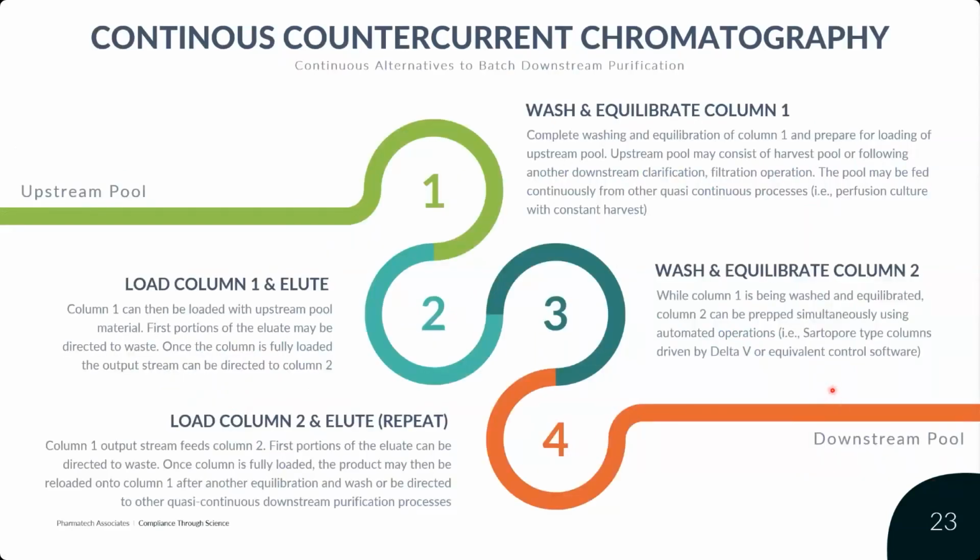And then really getting into other potential continuous ideas. I think the in vitro transcription upstream reaction can be made continuous through a continuous stirred tank reactor design, where reagents are continuously fed and then taken off the reactor. Being able to perform continuous chromatography steps downstream can be pretty valuable. Some ideas that can certainly be tried are to run two chromatography columns almost in a counter-current fashion.